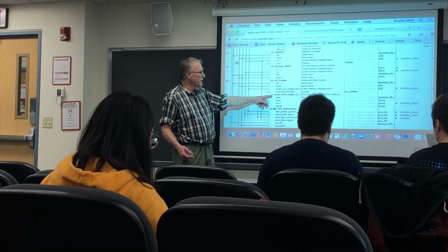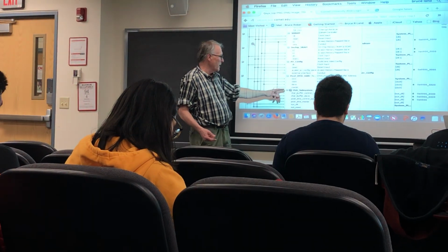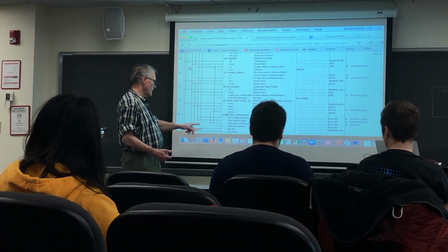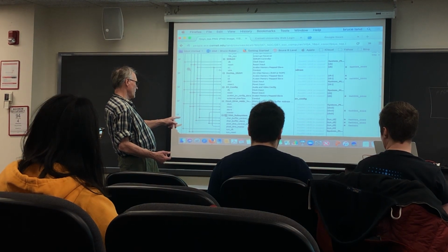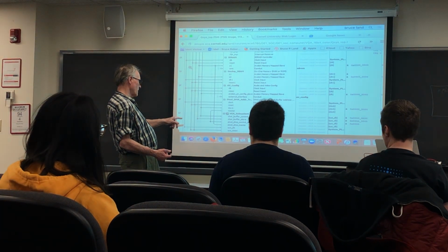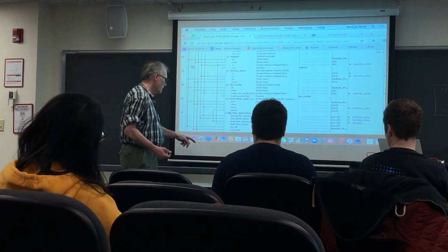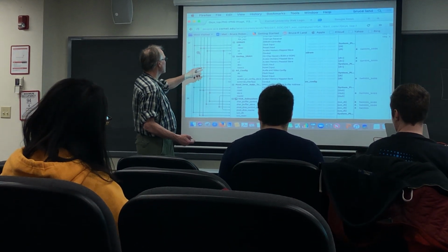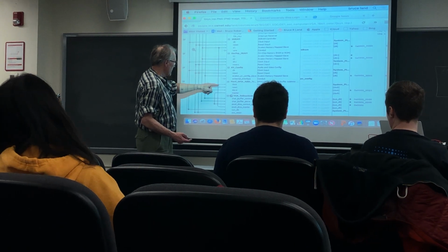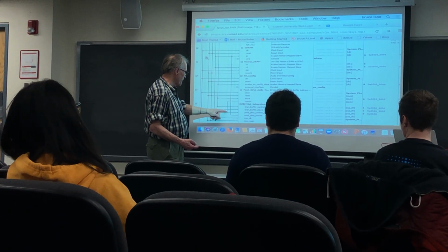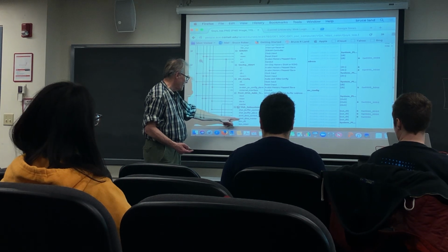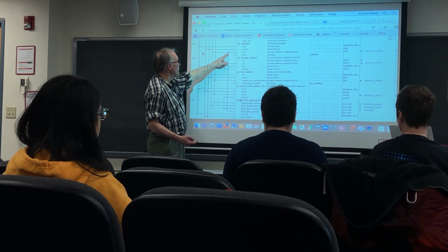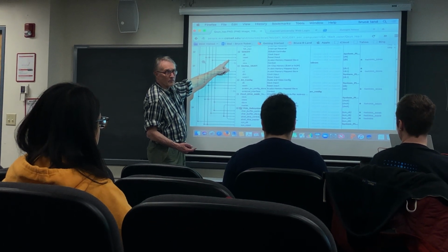DMA translator, pixel DMA controller, and the master for the DMA controller goes out to the VGA subsystem, and then the DMA master goes back up to SDRAM.